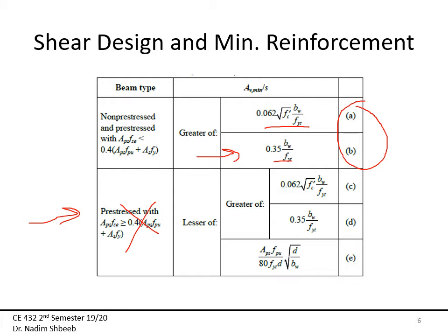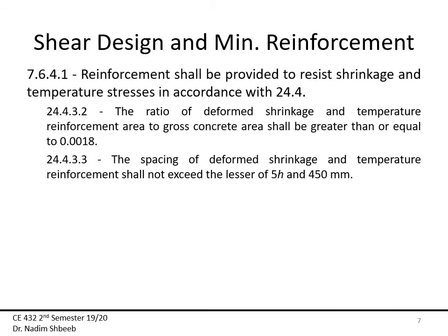Here I would like to point out that D over 2 and 600 millimeters does not apply to the solid slabs because that pertains only to beams and one-way rib slabs, by the way. Okay, so keep that in mind when we get to it.